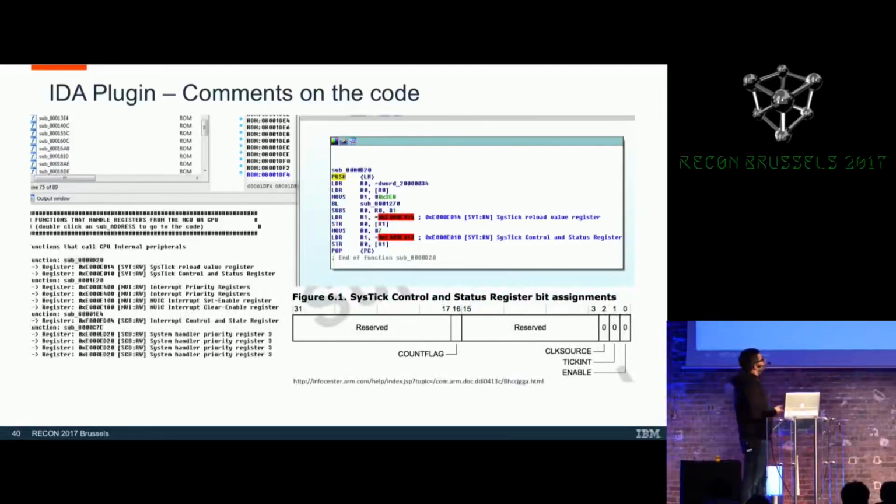So in this case, what this application is doing is that at every 1,000 clicks, it will generate an interrupt and it will wait. This is the kind of thing that you will find in the documentation of all MCUs. In this case, all MCUs based on the ARM Cortex-M0 will have this kind of clock, which can be configured however you want.